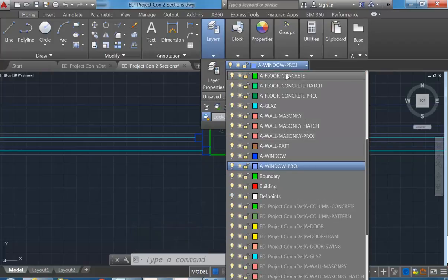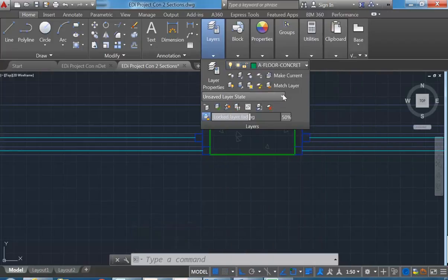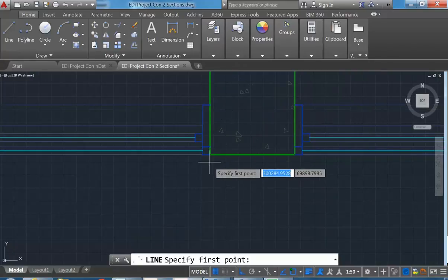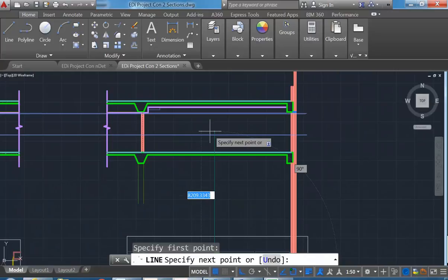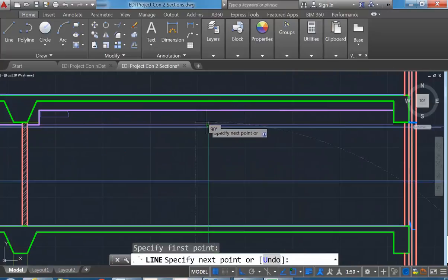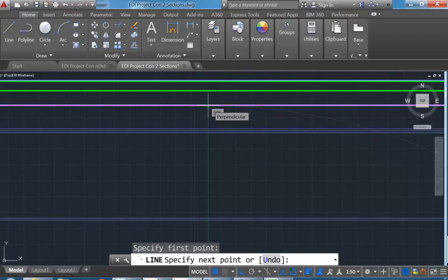So in fact there, it's optional here which layer you work on. You could do it on the concrete layer, because you do really see the edge of the column, so you could draw that first. So I'll just take that up to the bulkhead for now.